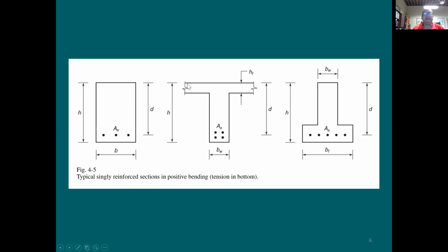Now let's look here at a T-beam. This is a T-beam because I have a flange. The thickness of the flange, the symbol that we use for it, is going to be either H sub F or T sub F. Sometimes you see it as T sub S, like slab thickness. HF is okay for the flange thickness. Depth is going to be the same, but look at the depth. Because we have 4 rebars, now the depth is going to be right to the middle of all of these 4 rebars. Because when I do the analysis, for me, this is going to be 1 tension force. I'm not going to do 4 tension forces here. It's going to be just 1 in the middle, at the CG of these 4 bars.